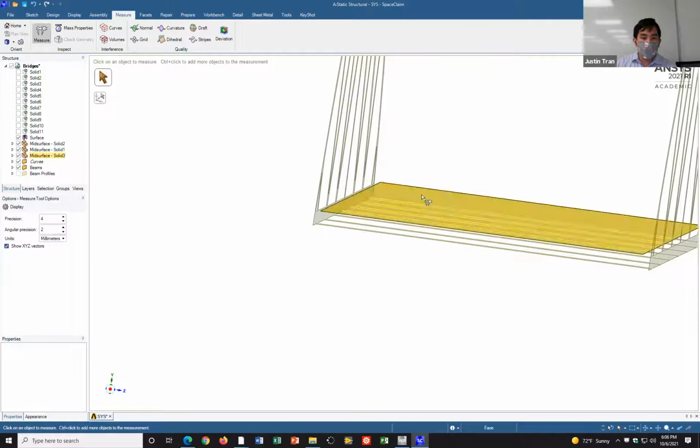First, let me right click on connections and hit insert. Then you're going to click on manual contact region. What this will do is allow us to define a contact region between two different bodies. You can see we've pulled up this new menu. In order to define a manual contact, we have to define the contact surface and the target surface, which are the two parts of the geometry that should be in contact with each other.